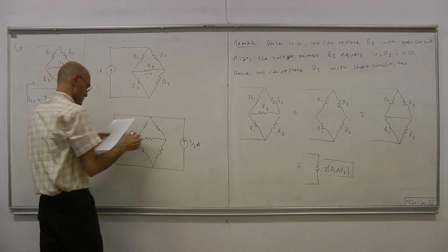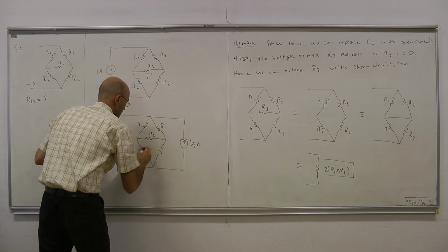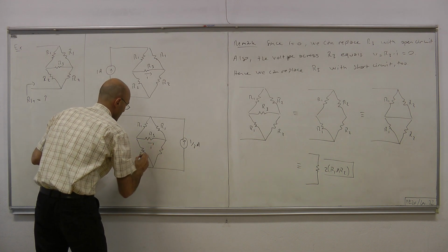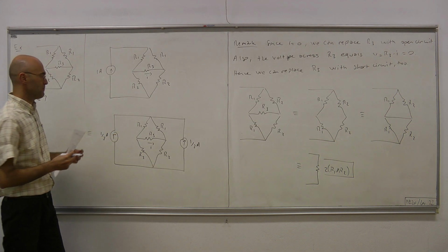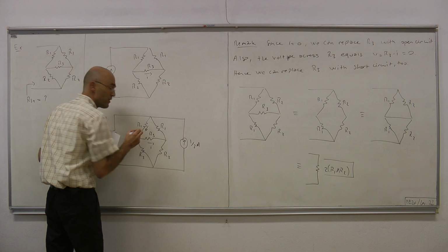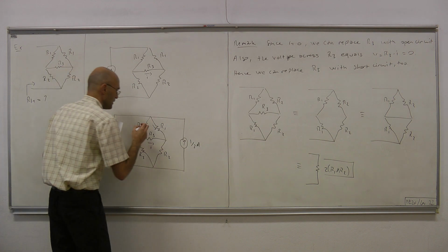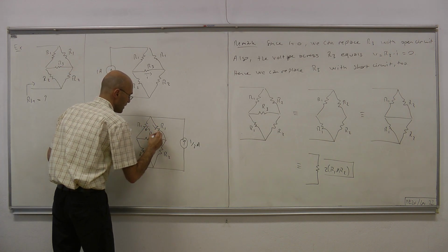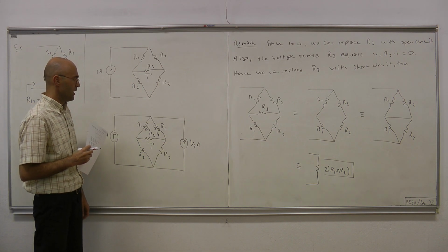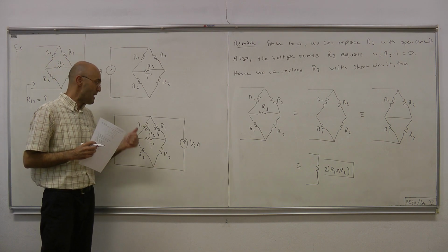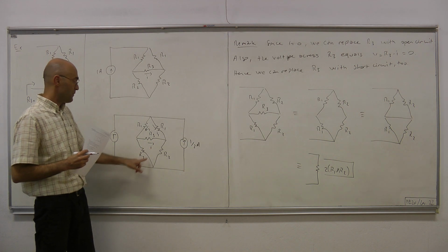Okay. So this is R1, R1. This is R3. This is the current that we're interested in, and these are the bottom resistors. Because of the symmetry, it's clear that whatever this current is, this current here must also be the same. So let's call those currents I1, and here we have another I1. It's the same current flowing over the R1s. And then, because those two currents are the same and these two resistances are the same, it follows from KVL that this current must be 0.